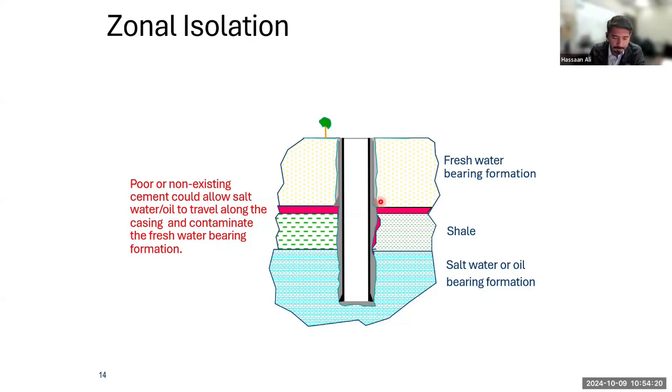That is so. Usually that is done once you have reached your desired depth. Once you have reached your desired depth, even if there is oil, it will not go into the borehole because you will have drilling mud over here. The drilling mud is there to ensure that there is no uncontrolled ingression or incursion of oil and gas into the borehole. Drilling mud is much heavier than the oil. It has more density, and it is made deliberately to be heavier so that it can exert that weight on the formation.